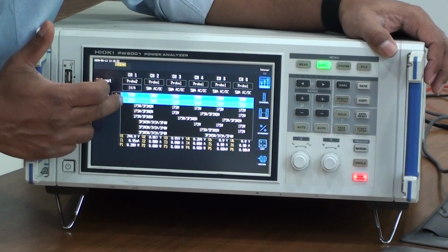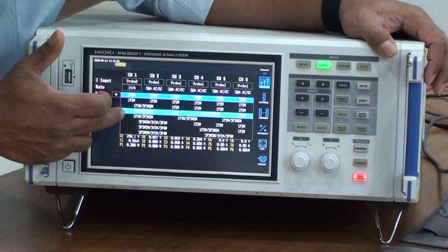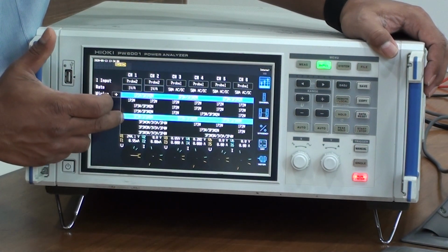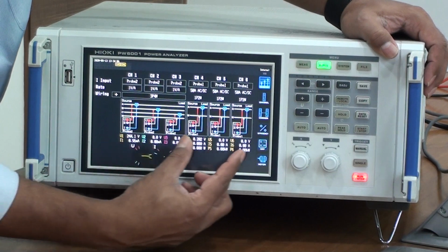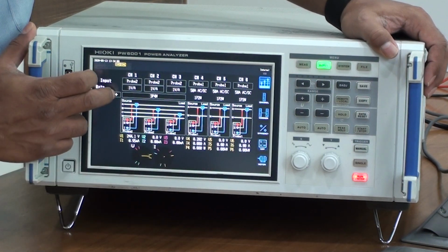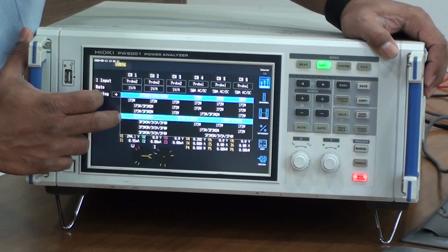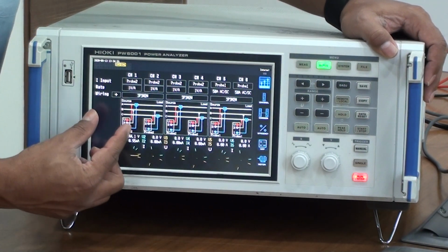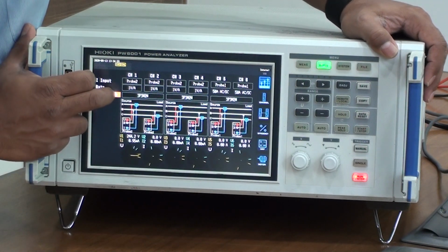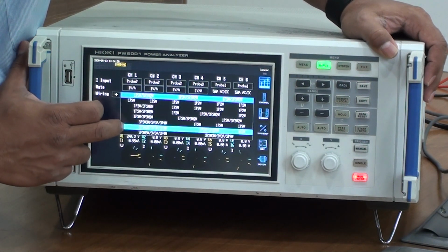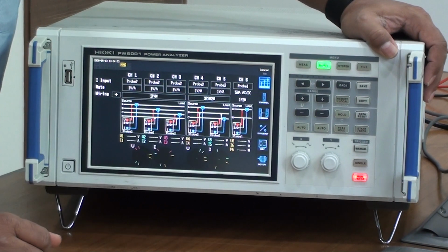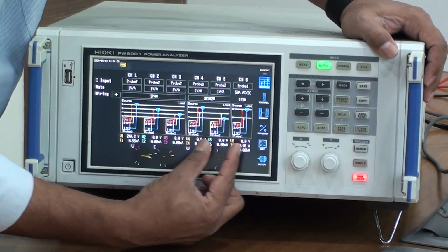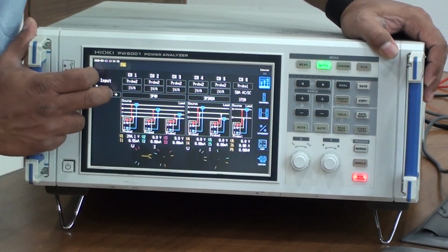Here you can configure the wiring pattern. Right now what you see here is a 3-phase 3-wire system where you will be able to have 3 inputs and 3 outputs. And similarly you can have one more system that has 3 separate 3-phase inputs. This is a 2 wattmeter method. We also have something that can go in for a single phase system, which means you can have a 3 input as well as a 2 input and a single input. So you can configure however you want.